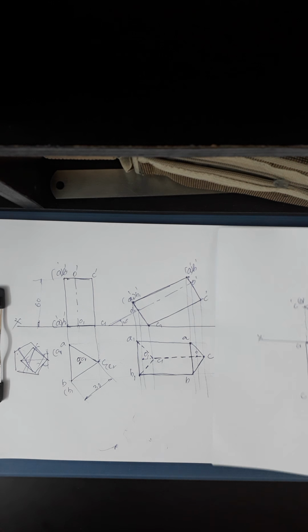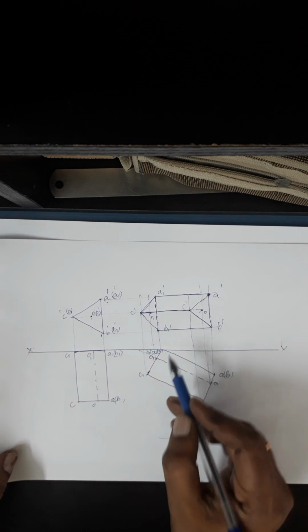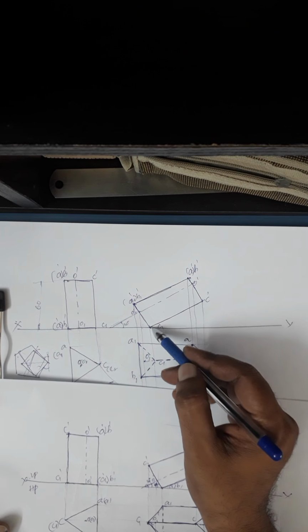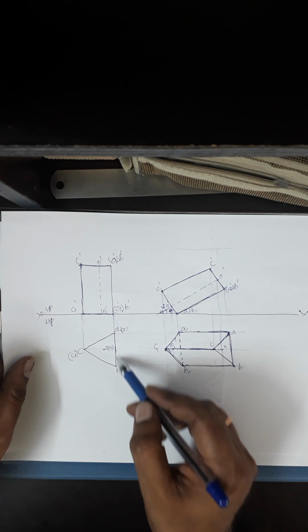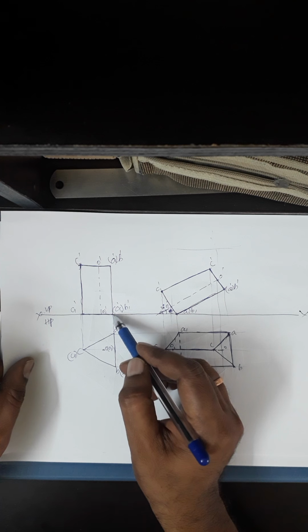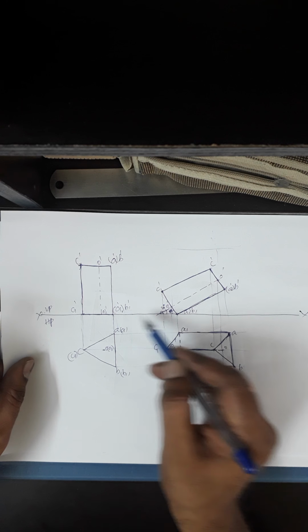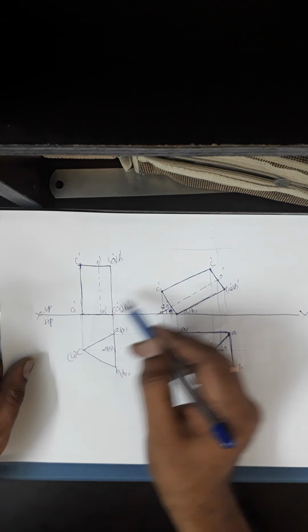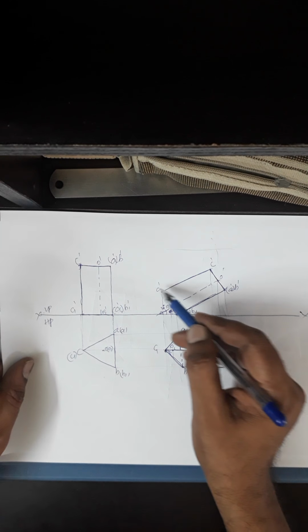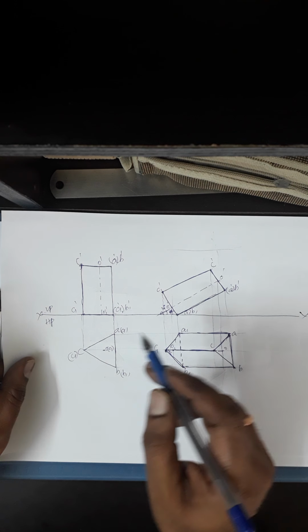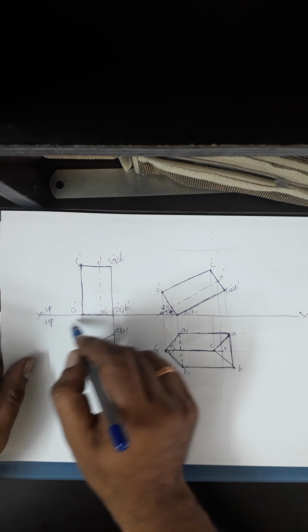So the axis inclined to HP can make the difference now. The earlier one is having one of its base edges on HP, whereas here we're going to have base corners. So in that case you can see that the base edge which is going to rest on HP I kept on the right side. I have constructed my polygon on the left. So I made that A1, B1, the base is to touch the XY line, which is nothing but it's resting on HP. So I have redrawn the same view in this position, then projected to get this view.